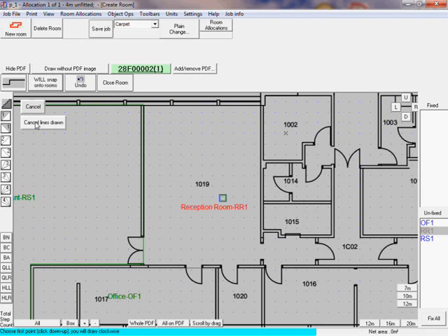We click on the I will start tracing round now button, and then click on the corner of the already drawn room that we want to align with. Because we are now snapping onto rooms, a green circle comes up to say that we will be starting exactly on the existing corner of the restaurant. This time we decide to trace anti-clockwise, and we get circles at points where we may want to align with existing corners.